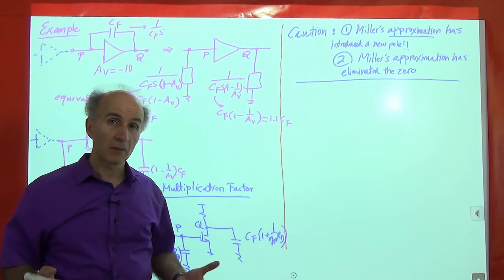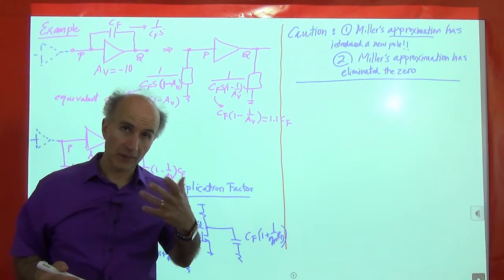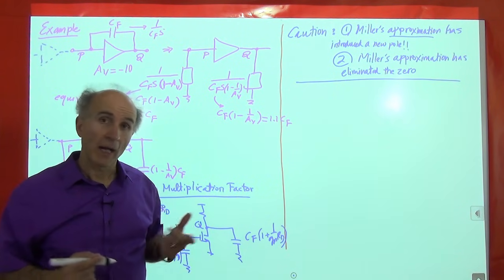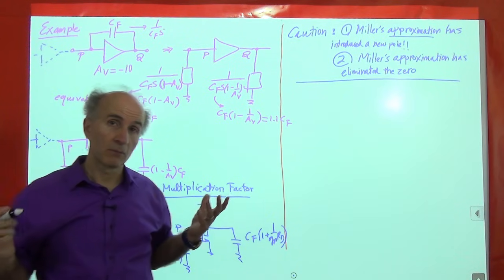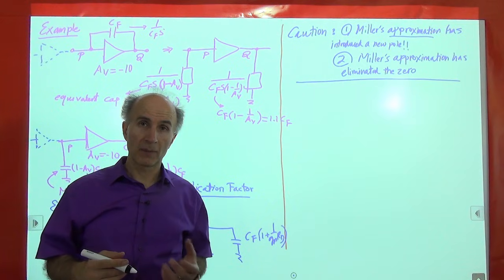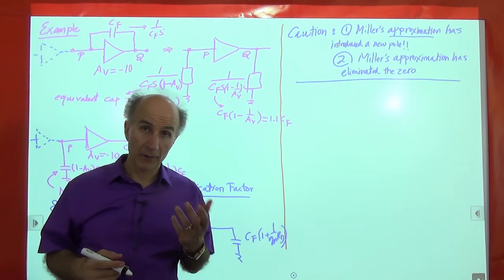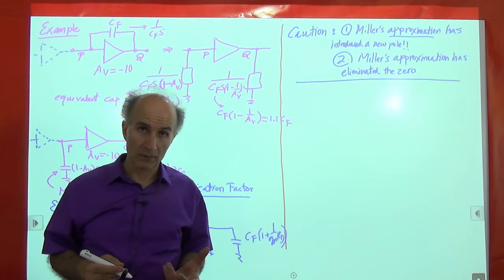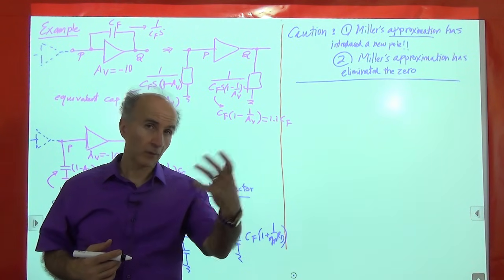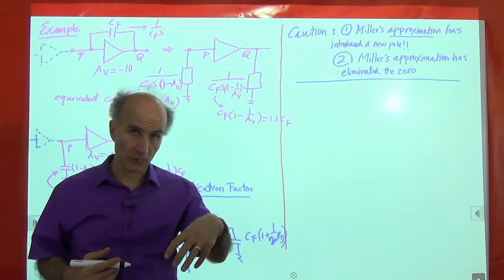So obviously we need to identify all of the capacitors that we encounter in a circuit and then see how we should deal with them. And the most common type of capacitances arise from the components themselves, in particular from the transistors. So I need to identify, when I see a bipolar transistor, what type of capacitances it introduces into the circuit.